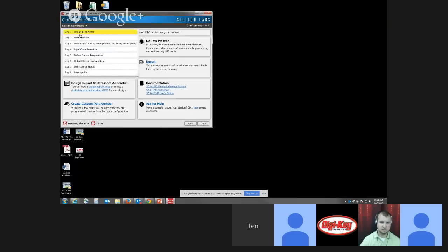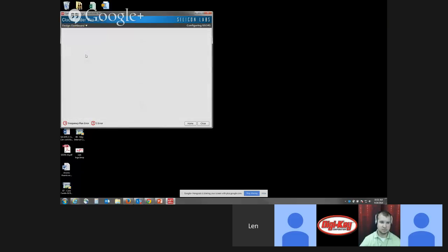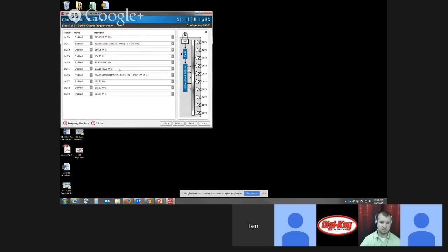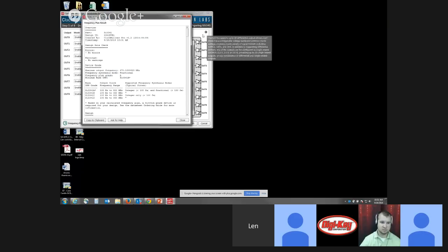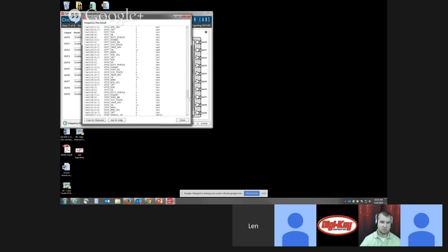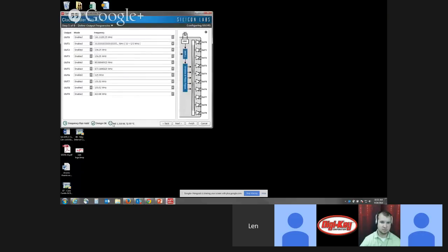So just to give you an example here, if I were talking about the output frequencies and I didn't generate something too crazy here, let's say I had 1 megahertz here. If I put something nutty in there, it says, hey, your frequency plan is valid. It gives you a little report here as to why you might have warnings or whether it's good or not. Gives you a power estimation and whatnot.